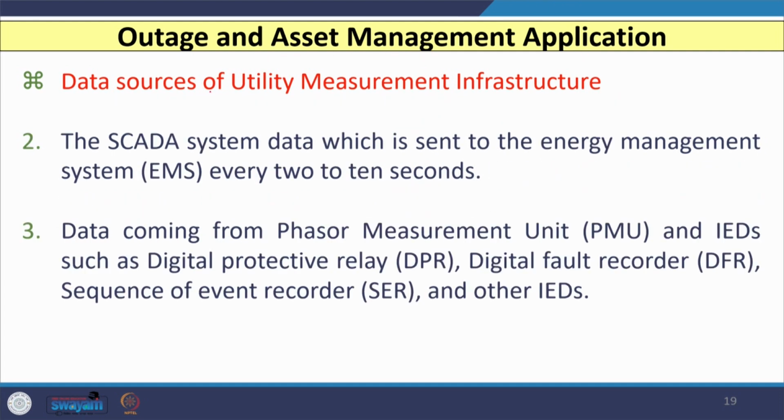The SCADA system data are also there, and this data are useful for the energy management system algorithms. The third is the data available from PMU, IEDs, or maybe you have, let us say, data available from digital relays, or maybe digital fault recorders, or maybe the sequence of event recorders and several other IEDs. So, those data are captured by the utility.